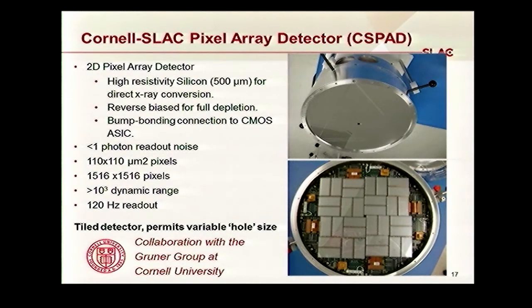And in parallel, there's a very large effort in developing the detector for a free electron laser. It needs an imaging detector which can read out at the repetition rate of the Linac, which is 120 hertz. So imagine this is a few megapixel detector, about 2.3 megapixels, running at 120 hertz. The data rate is a tremendous amount of data. I won't have time to go into that, but there's a huge amount of effort now going into handling the amount of data you get and how you get the most information out of the data you generated.